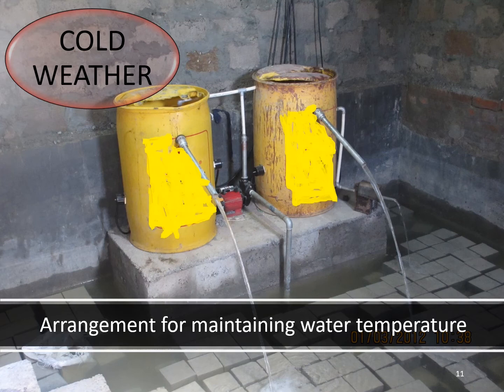possibly your initial strength will also indicate very low, which will be misleading, and you will always be in a worry whether your 28 days strength will pass or not, or the later days strength will pass or not. So it's always required to maintain the temperature of water when it is in the cold climatic conditions.